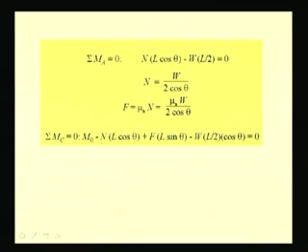So, these are taken care in this moment equation, and by solving this equation we know these values, that is N, the frictional force F and W. So, we get this required moment, and the required moment is 0.818 times WL.